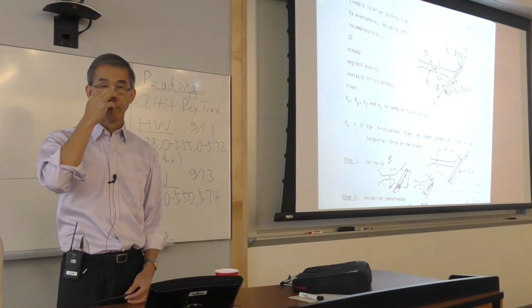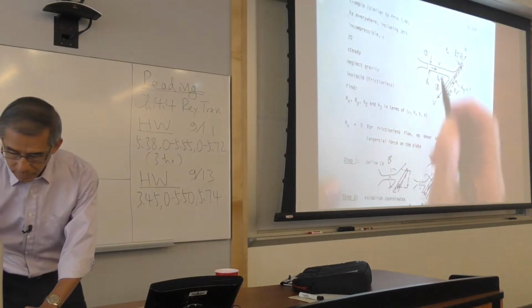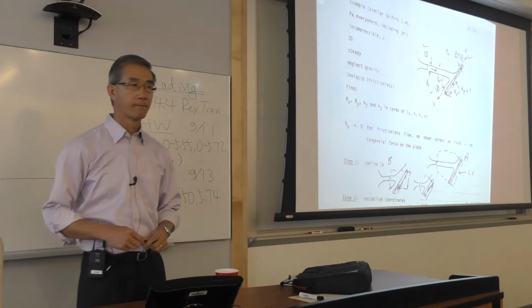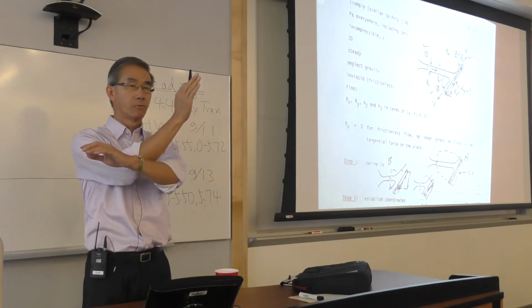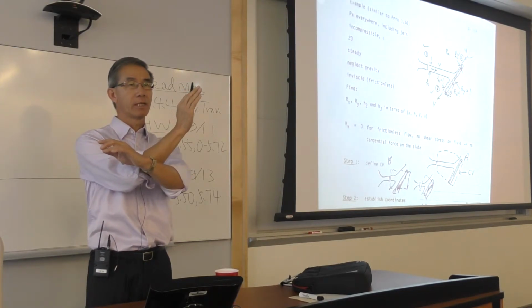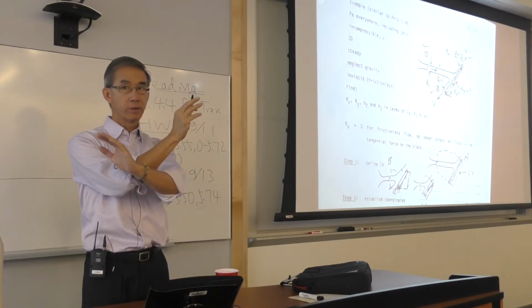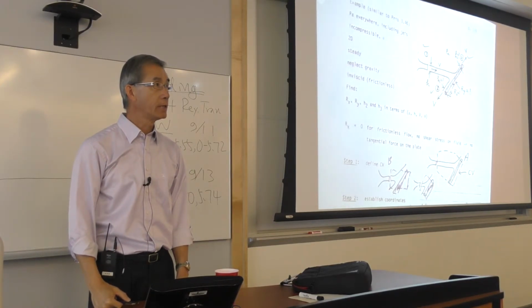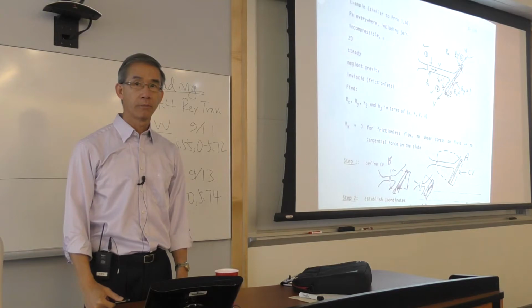Yes? The interfaces are perpendicular to the surfaces given. By choosing A, at all the control surfaces at stations 1, 2, and 3, what is the relationship between the velocity and the area? On all three faces, they're perpendicular. So how would that simplify my use of what equation? The continuity equation. Okay? So by choice, I'm picking this control volume A so that I can take advantage of the fact that velocity and area at all stations 1, 2, and 3 are perpendicular to each other.